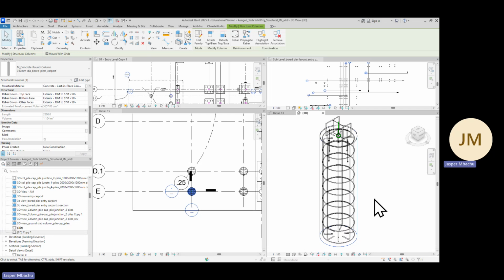Oh, okay. Yeah, sorry. Can you do VG? Click on that, and type VG. Then look for the bars, which are called structural rebar. Tick structural rebar. Maybe that's why it's not displaying. Yeah, and say apply.